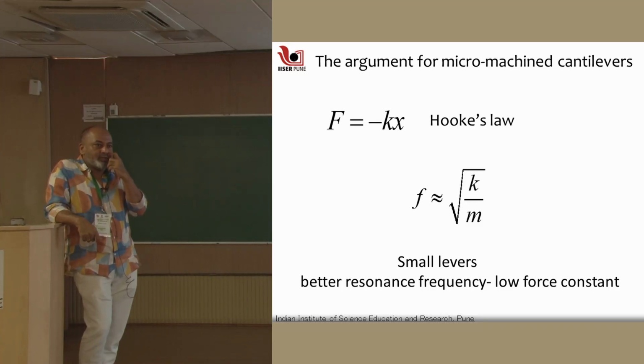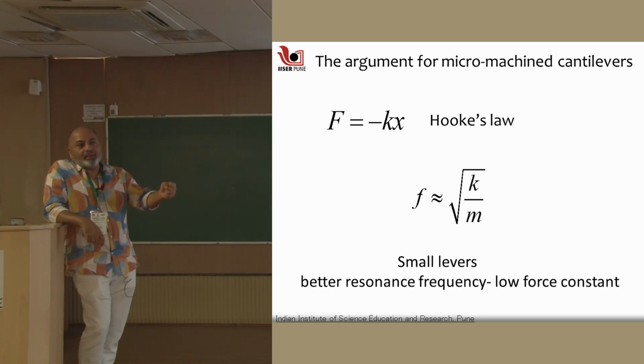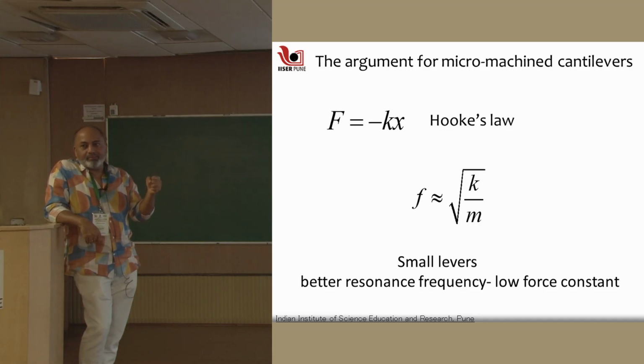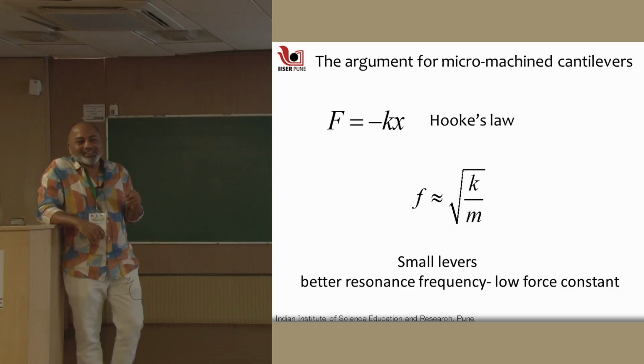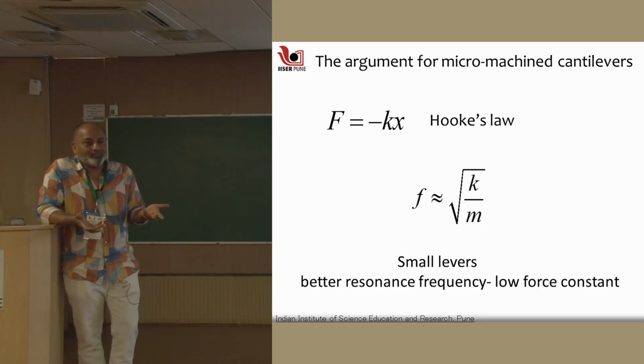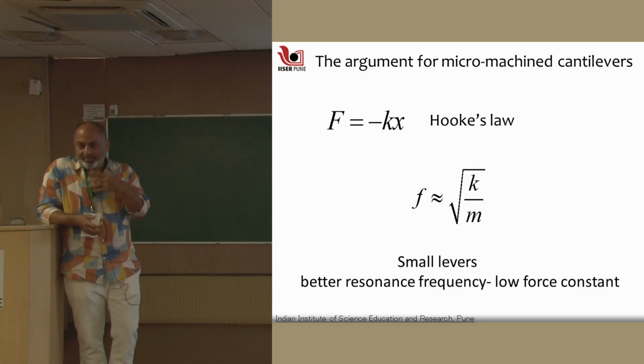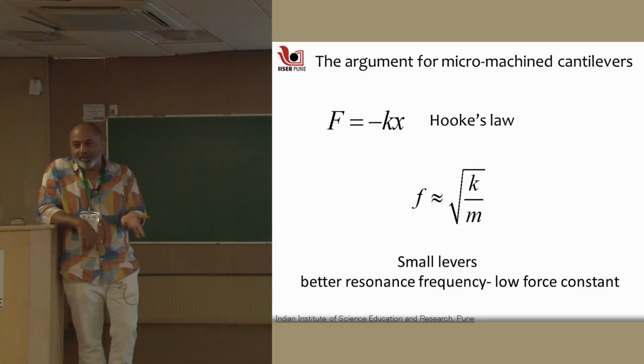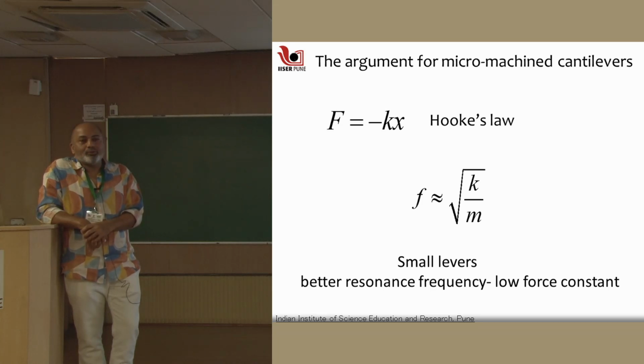What is the typical stiffness of a spring that you are used to? Let's say I have to weigh 1 kilo of sugar or salt or onion or whatever. 1 kilo means how much force? I will keep asking this, otherwise you will fall asleep. 1 kilo weight is how much force? Anyone can say? Kilo is mass, no? It's just 1 kilo mass. Yeah, you have to multiply. Let's say 10, or 9.8, it's close to 10. So 1 kilo will be 10 newtons of force, right?